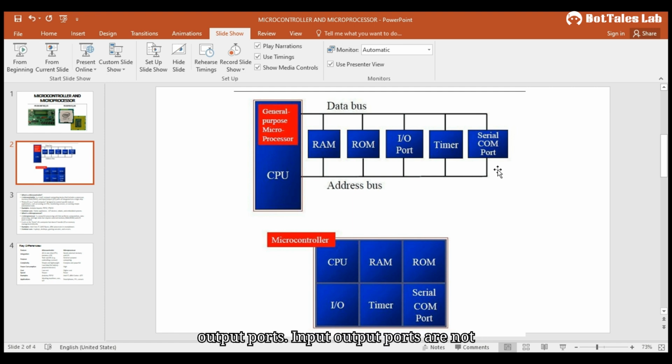Input output ports are not available in a microprocessor, whereas in our microcontroller, everything is integrated on one chip, that is CPU, RAM, ROM, input output ports, everything is available on one chip. That is, if we want to store some information or data in our microcontroller, we can store it in its inbuilt RAM or ROM. And if we want to connect some external devices, we can connect them by using input output ports that are already available in a microcontroller.